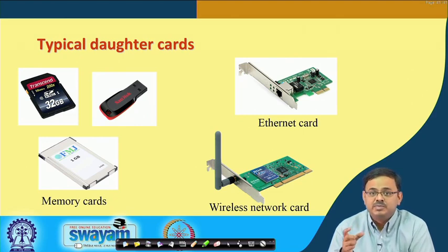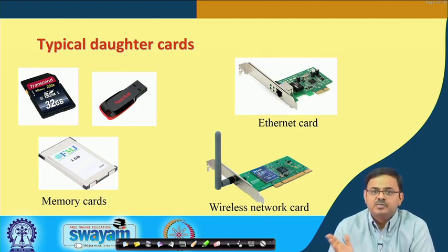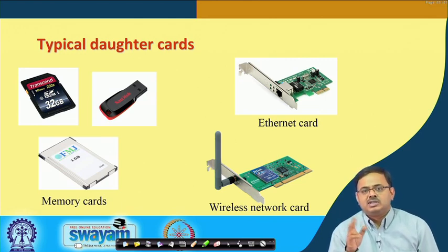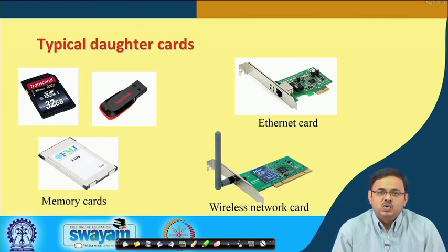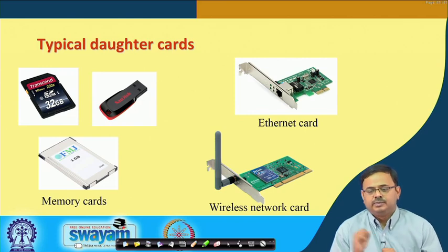Just a side note here, you may also argue that especially for a pin grid array or a land grid array on which the CPU is resting, these are also removable. These can be attached on the motherboard and removed, okay, the removable part, correct. So, one can argue that well, can I say that these packages are like daughter cards? Not necessarily, and you can say whatever you want. We typically do not call them daughter cards or circuit cards. Okay. These are packages specially designed to house a high performance piece of silicon or a high performance chip. Okay. All right.